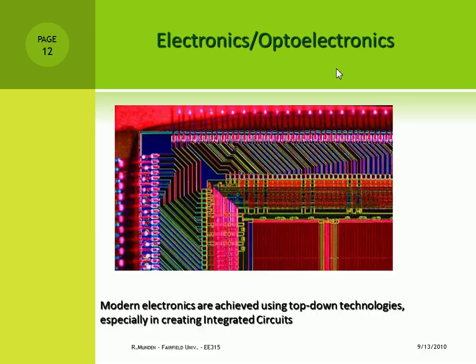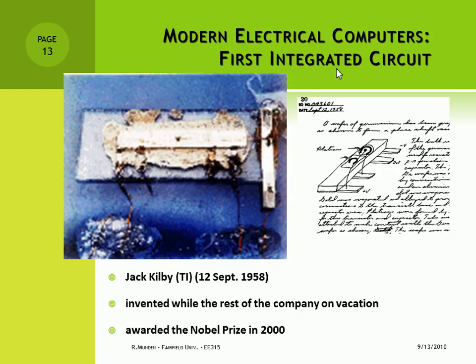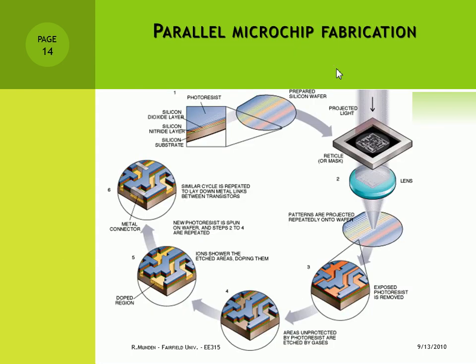So this top-down idea, right, we're used to making microchips, right? And we combine electronics, optoelectronics, everything from LEDs and photodetectors. We do all of this using integrated circuits, which were pioneered by Jack Kilby, right? Back in 1958, here's the first integrated transistors on a piece of silicon. There's 2 of them in there, right? And now we've moved on to having billions on a chip. And this is done through this idea of photolithography. This is really the workhorse of integrated circuit fabrication, right?